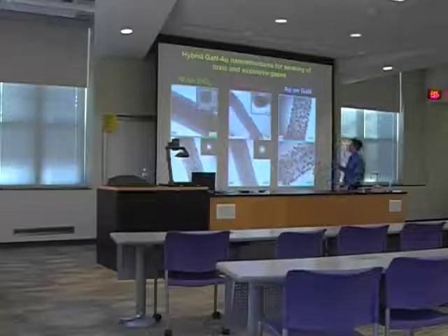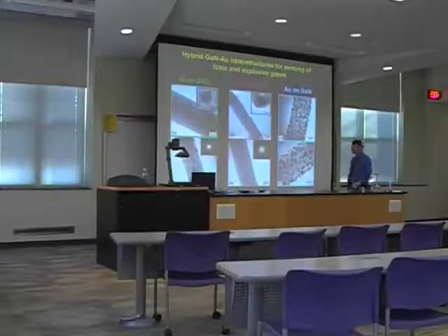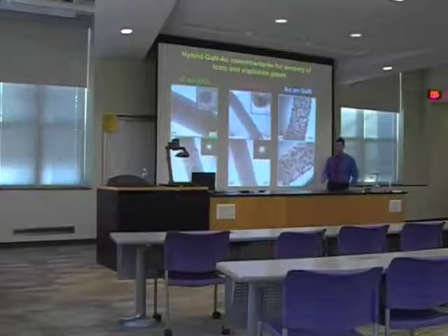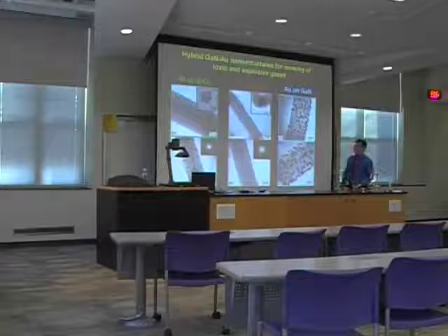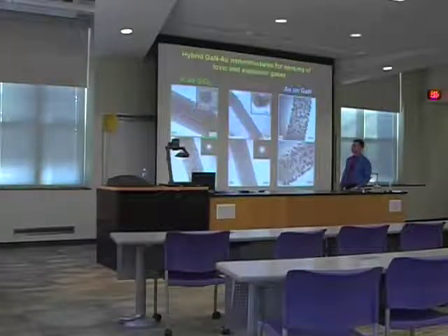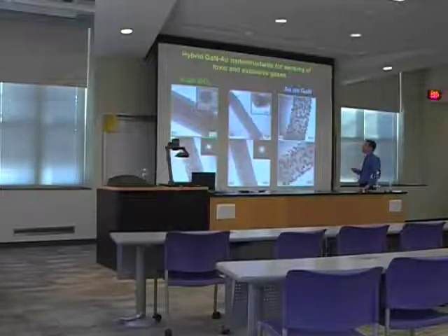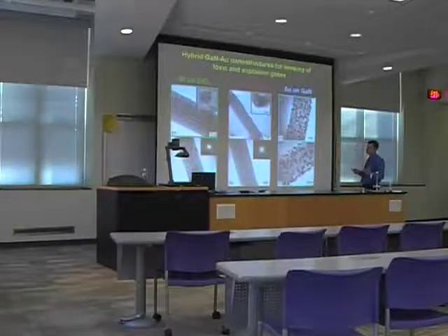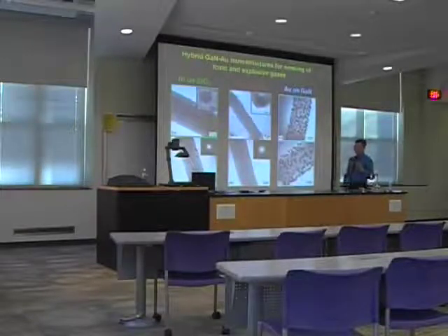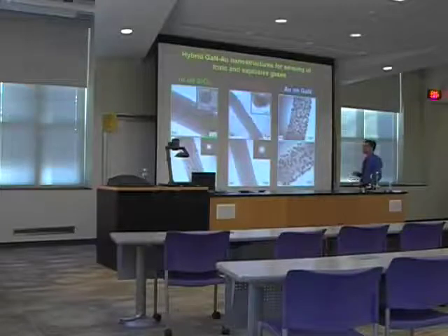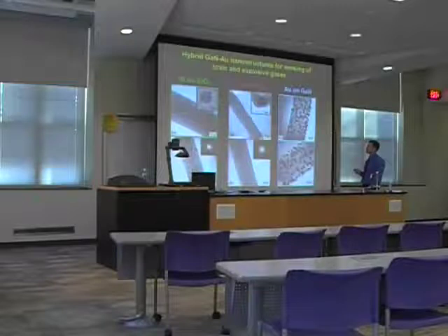If we speak about gallium nitride, this is decomposition of ammonia in presence of gallium. So in this case, if you put a small quartz wafer inside the tubular furnace, ammonia will decompose into nitrogen and hydrogen. Hydrogen will evaporate as a light gas, and nitrogen will react with gallium, forming this kind of nanowires.